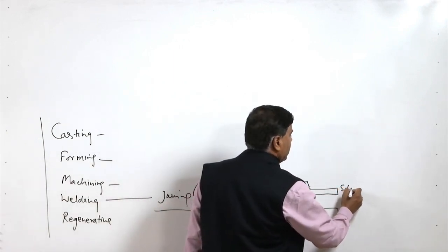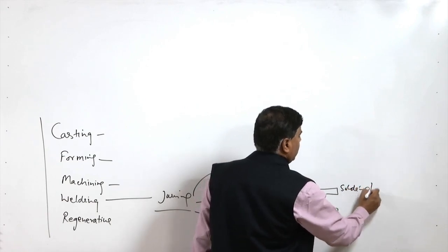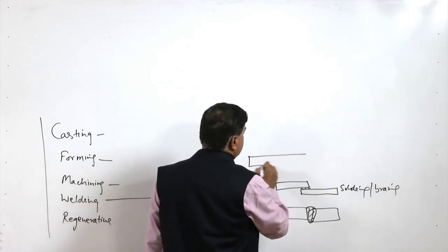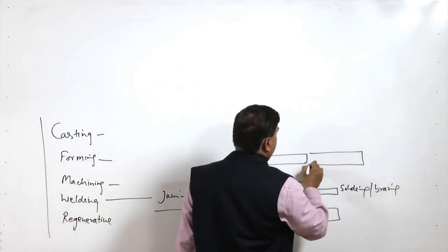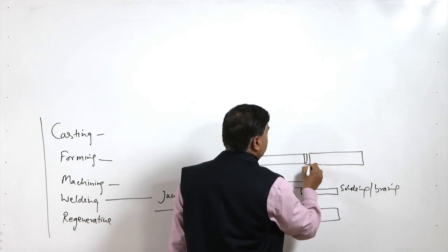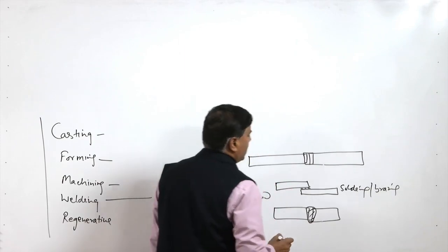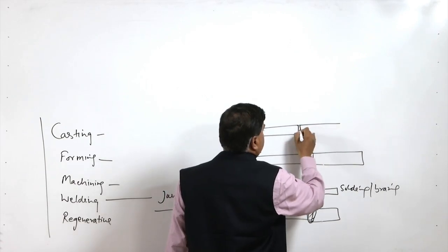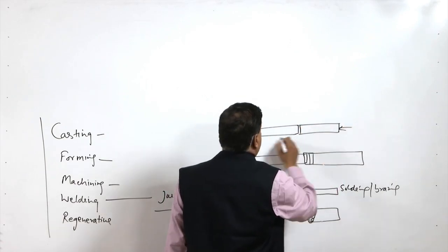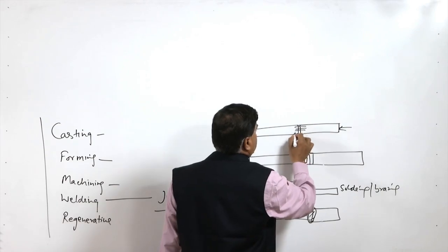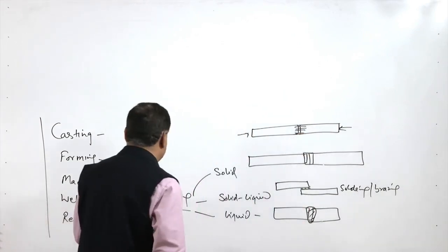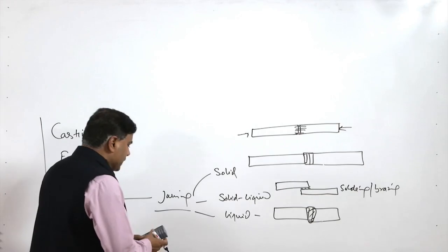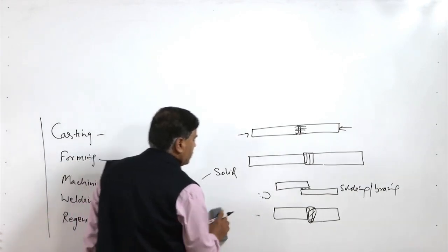Processes like soldering and brazing fall in this category, while in case of the solid state joining processes, the components are maintained in the solid state and the application of force helps to have the metallic continuity, or we can use processes like diffusion, where cleaned polished surfaces are kept under pressure at a high temperature, so that diffusion across the interface takes place to have the metallic continuity. So, the range is so wide that it allows very good features to the joining.